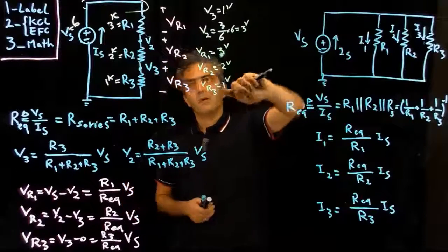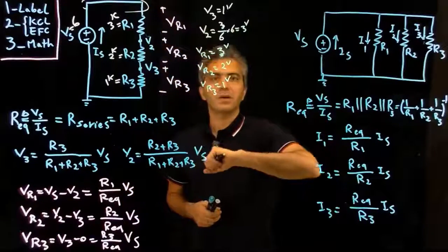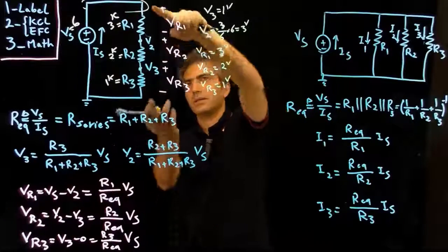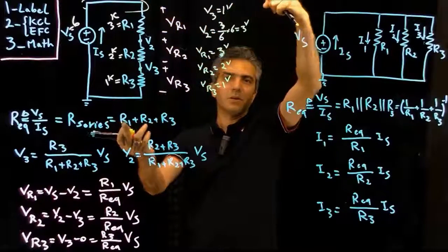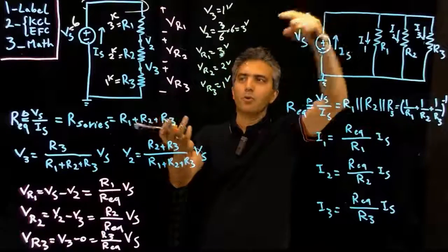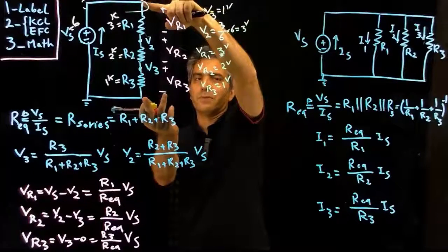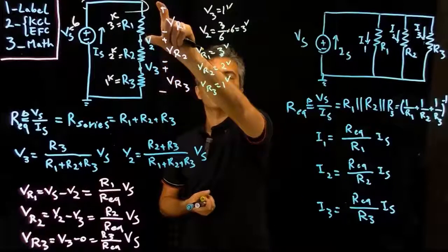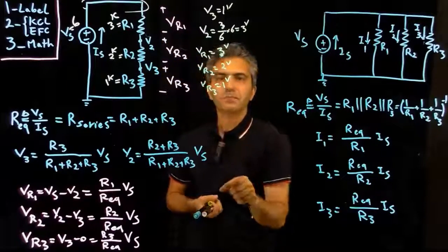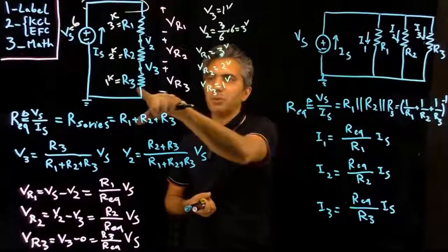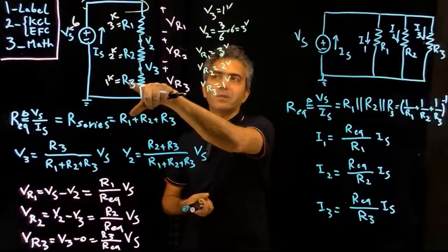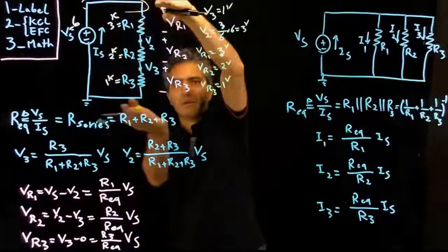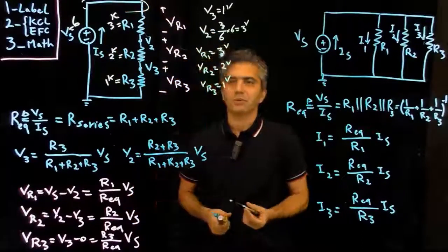So if you notice the voltage difference across each one, when you add them up, ends up being 6. Obviously, it's going to add up being the total voltage difference across the whole thing. But also, the value of the voltage across each one is basically proportional to the value of the resistor over the total resistance multiplied by the whole potential across.